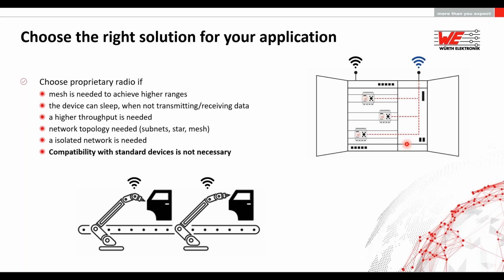Sorry to disappoint you. There is no one-stop solution for all the requirements, which means typically you choose the wireless connectivity solution based on the demands of your application. Let's say you have an application where you are transmitting from this robotic arm to a central device here. You don't have too many data rate requirements, which means you have smaller sensor data packets. You have a requirement to build a mesh network, which means the right choice for your system is a proprietary wireless communication standard.